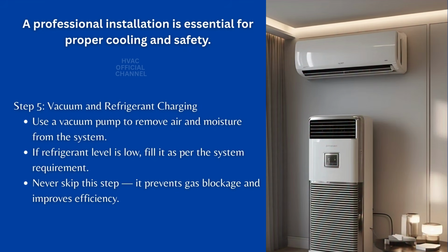Step 5. Vacuum and refrigerant charging. Use a vacuum pump to remove air and moisture from the system. If refrigerant level is low, fill it as per the system requirement. Never skip this step. It prevents gas blockage and improves efficiency.